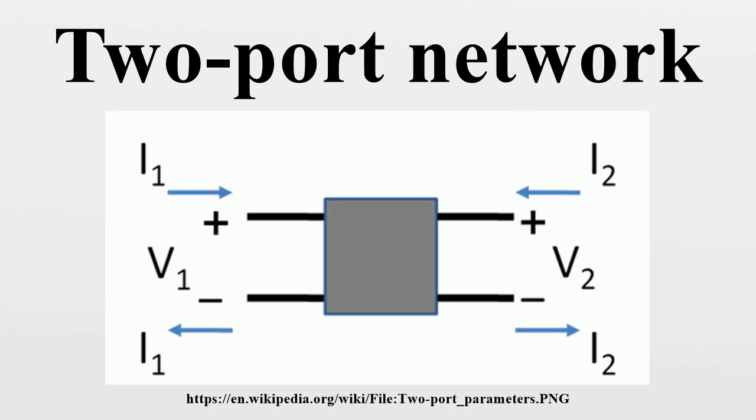Parallel-series connection: when two ports are connected in a parallel-series configuration as shown in Figure 15, the best choice of two-port parameter is the G parameters. The G parameters of the combined network are found by matrix addition of the two individual G parameter matrices.